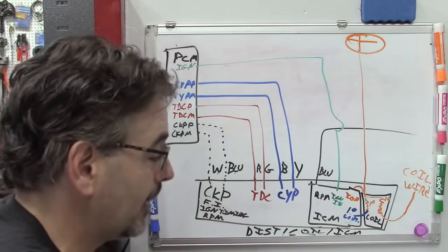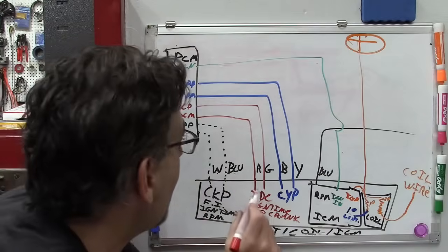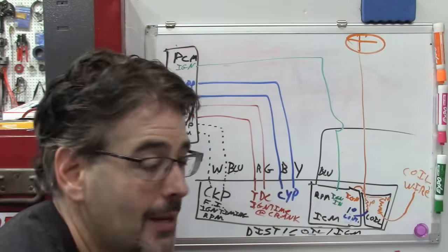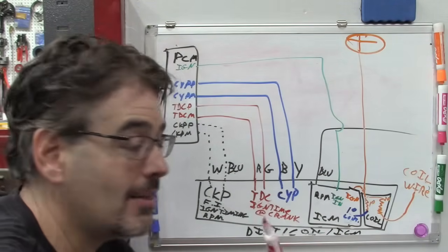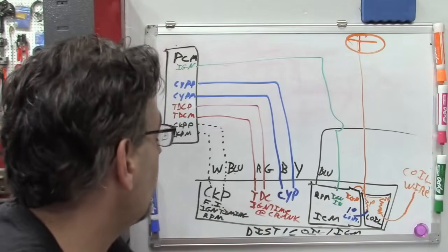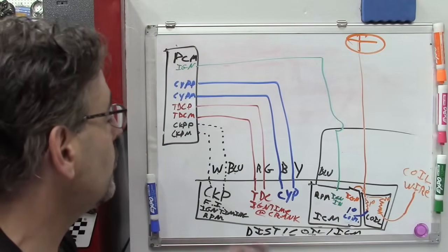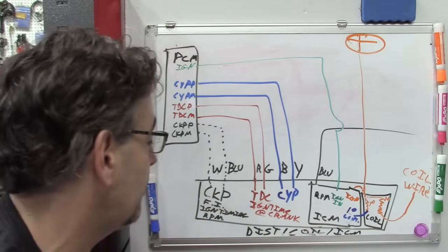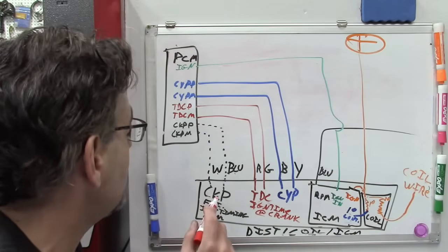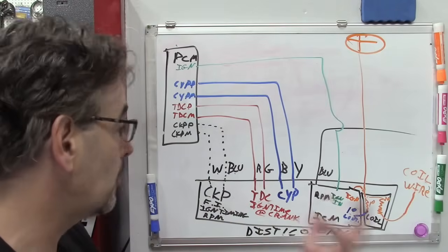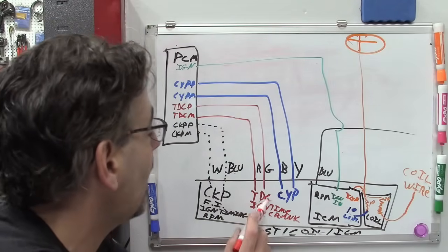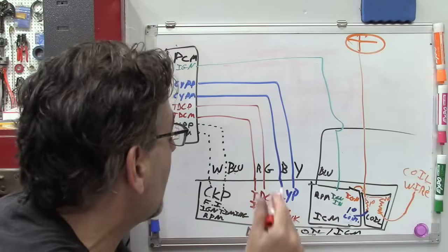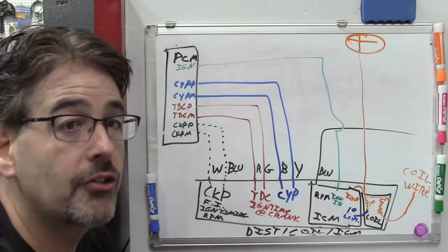Whatever the case is, the top dead center position sensor determines the ignition timing while cranking the engine. It also has a secondary feature, and it's to determine if there is some issue with the signal from the crankshaft position sensor. So my guess is while the crankshaft position sensor is going to be outputting a signal, it is actually the top dead center sensor during cranking where the spark timing is determined.